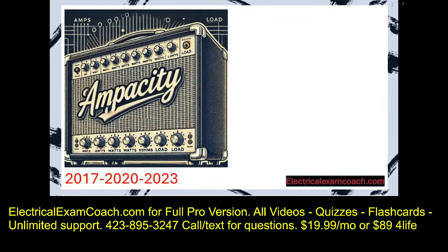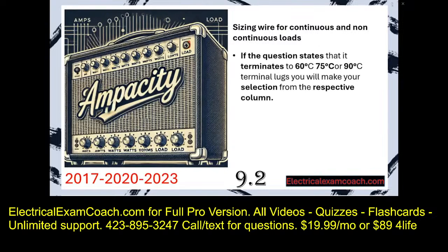Hey everyone, welcome back. I am the Electrical Code Coach from electricalexamcoach.com, and this is lesson 9.2 in our video series. In this lesson, we're going to be sizing wire for continuous and non-continuous loads. Let's recap on the basics before we get started. If the question states that it terminates to 60, 75, or 90 degree C terminals, we're going to make our selection from that respective column under normal circumstances.